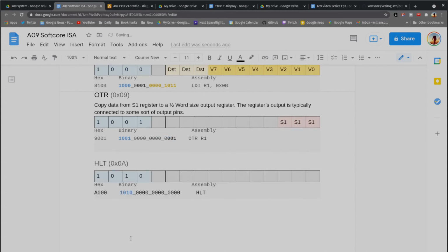The halt instruction is another one of the inherent instructions. It's very simple. The code itself tells the processor exactly what it needs to do. And in this case, it abruptly halts the processor. Nothing else happens. The only way for the processor to resume operation is by issuing a reset.